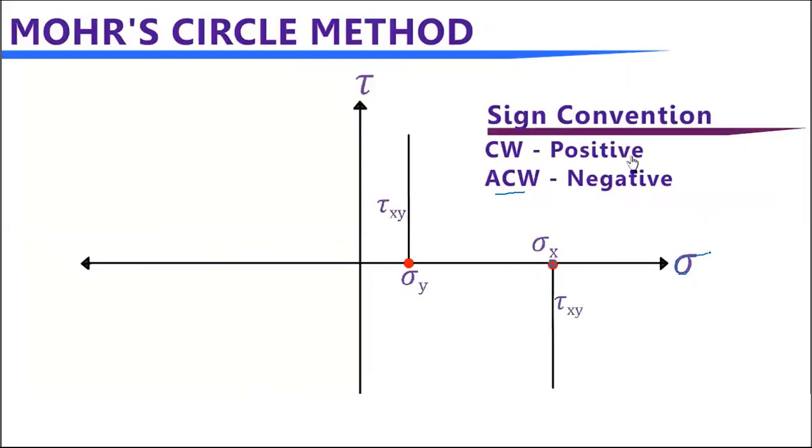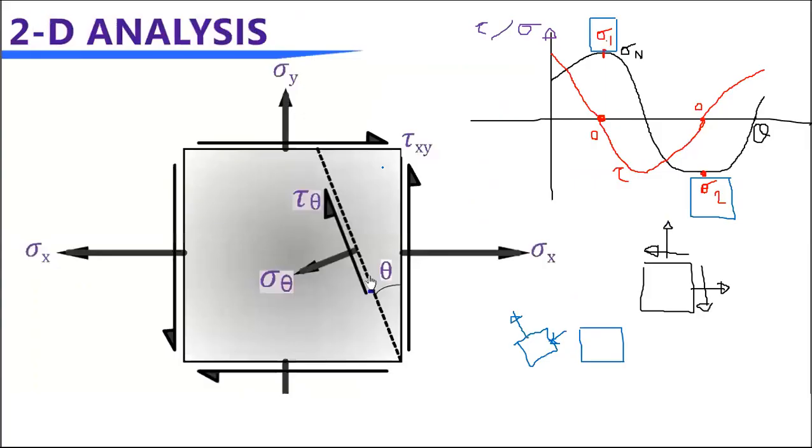So this is the sigma axis and this is the tau axis, normal stress, okay? And this is shear stress, okay? We usually call it sigma, okay? No need to put n. So this is positive but the shear is negative, so you have the point here. Here it was still positive tension, right? We don't know, this might sometimes be larger.